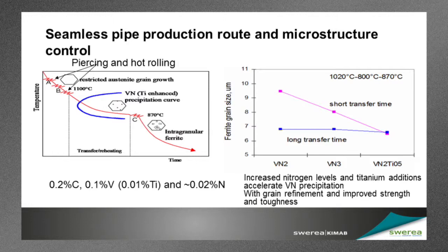Provided that the transfer time is sufficiently long, then this won't matter. We will get a good fine grain size under all the conditions. The result of this treatment is to improve the strength and also the toughness of the final pipe product.